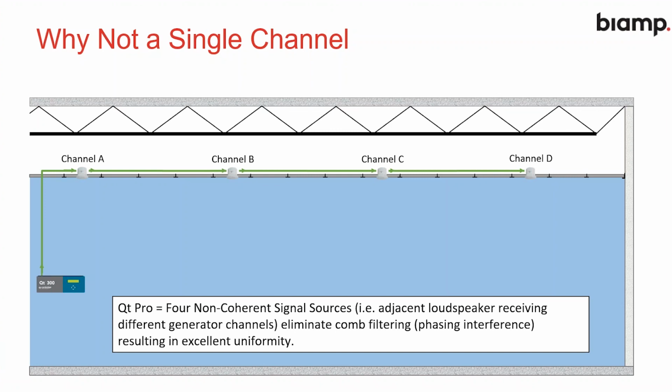Just at this point, I'll take a couple of questions that are relevant. How do we address deployment that requires more than 6 zones? To do that, we would quite simply have another 6-zone controller or a 3-zone controller. And there is a second question, from Robert: is it the same for a partition that goes all the way up to the soffit? We treat the ceiling height as the ceiling height. So whatever's going on above the ceiling does not matter in the direct field. We're only concerned with the area below the ceiling.